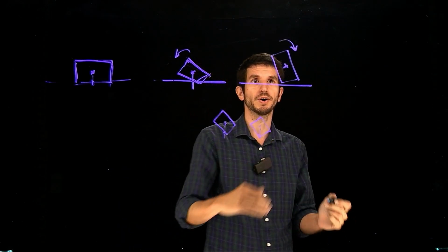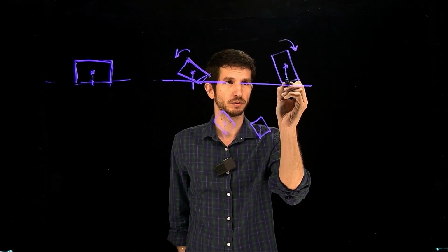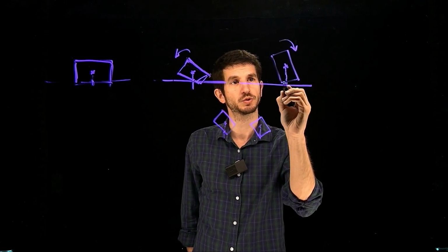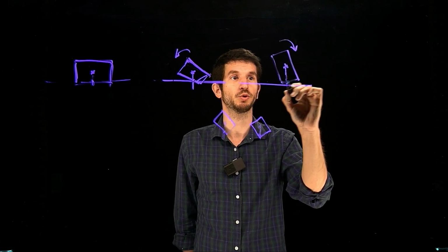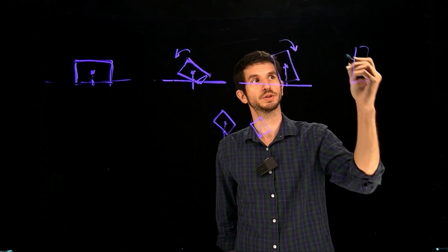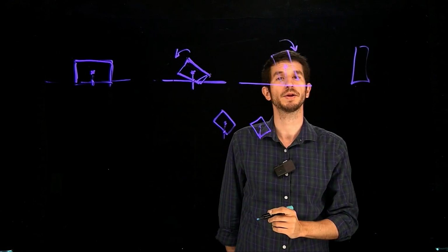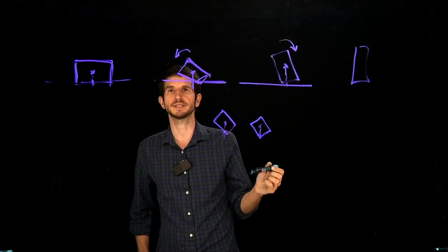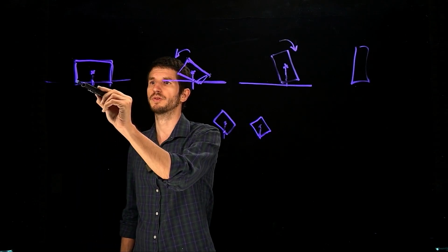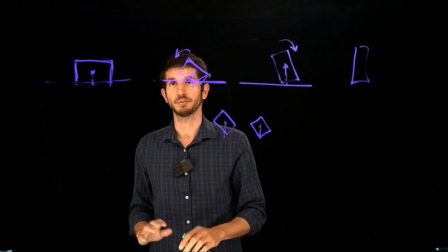The moment I go farther, the center of mass, when I go down, doesn't fall anymore through this layer, it falls in this one. So now the new equilibrium is going to be to fall in that one. That's equivalent as if I had this object and I was pushing that way to turn it that way. So the criterion of stability is to take the center of mass, make a line all the way down. If it falls within the base, then it's in equilibrium. If not, it will not.